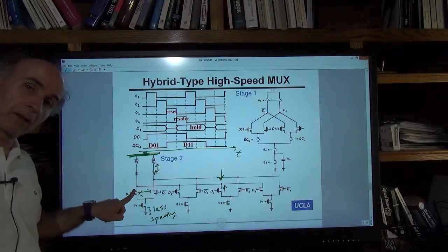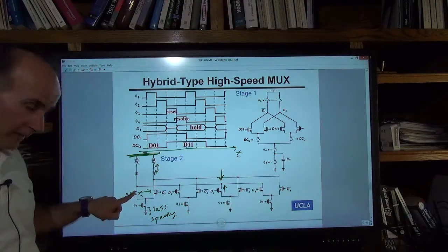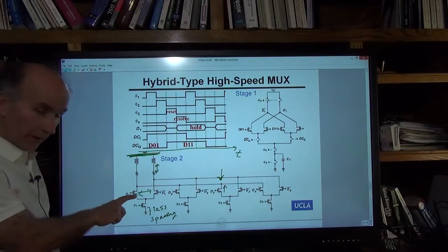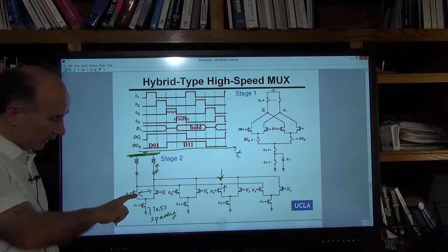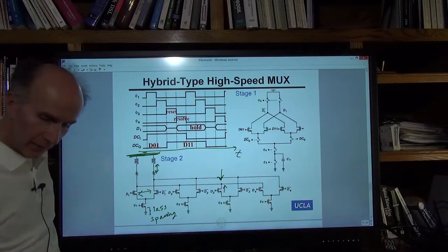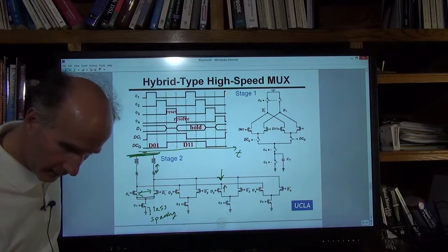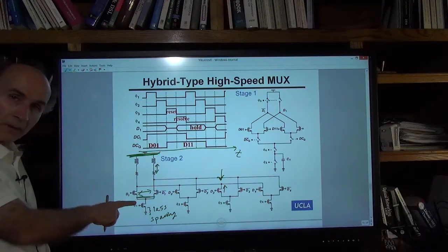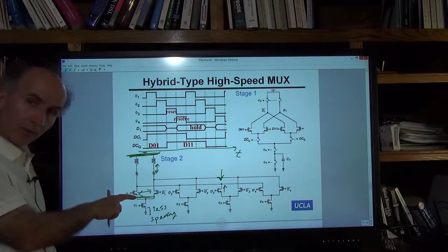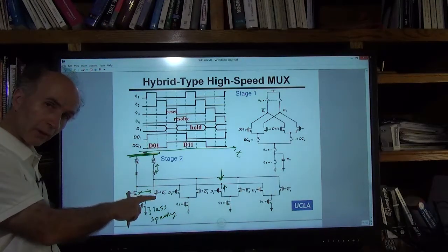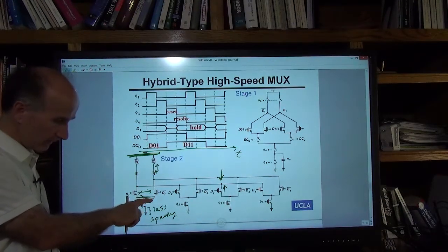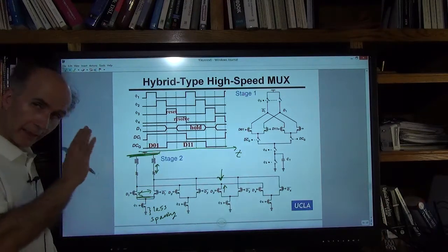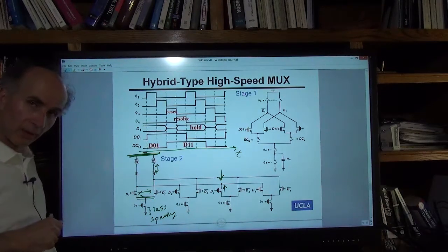So I have a differential pair in that symbols file as an example. And you can see that I click in iDraw near this arrow tip, and then I go straight, meaning that the line actually goes like this. It's not so far down. It's the first grid available below this arrow that allows you to make a right turn, left turn, right turn, and go this way and then come back up. So that saves you 1 grid spacing here. Okay, everything will be shifted up by 1. And again, every one of these matters eventually, as you will see later in your life.